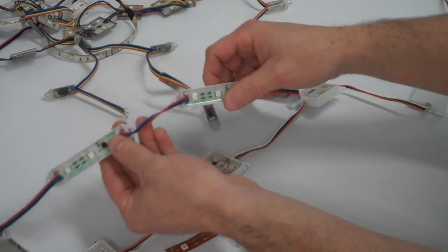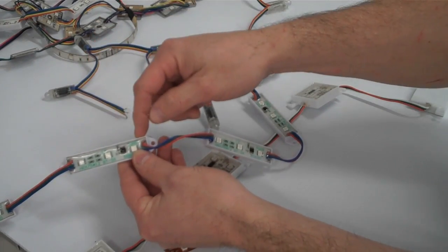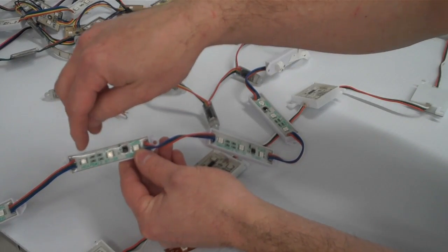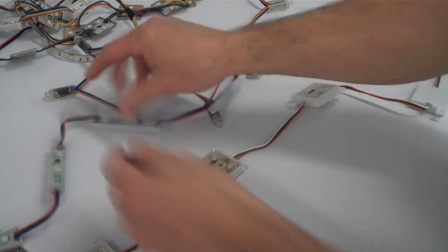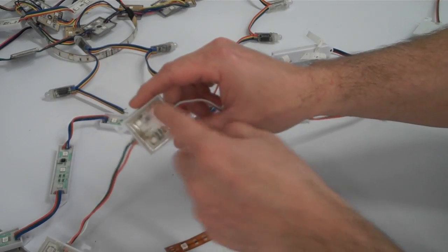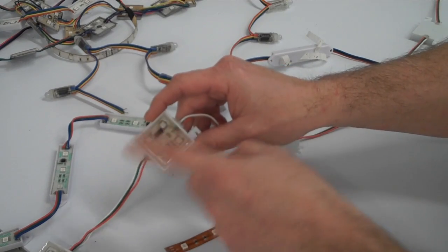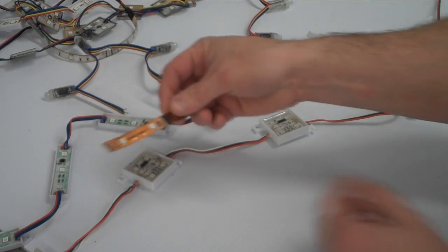Or, if we have modules, that means that this entire module, which contains 3 5050s, can be controlled. So there are 3 channels here. The 3 channels would make all of these red, all these green, or all of these blue. The same here, just physical differences in the number of LEDs. 4 LEDs, I can make them all red, all blue, or all green, or mix them to make any other color. It also applies to strip.